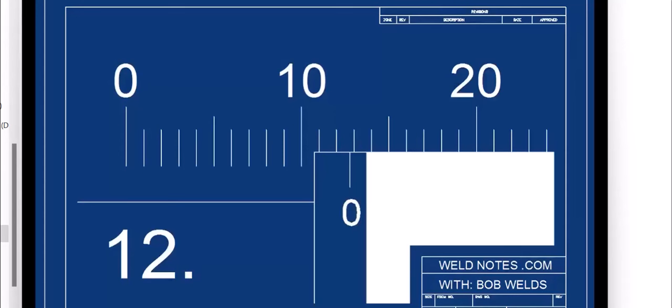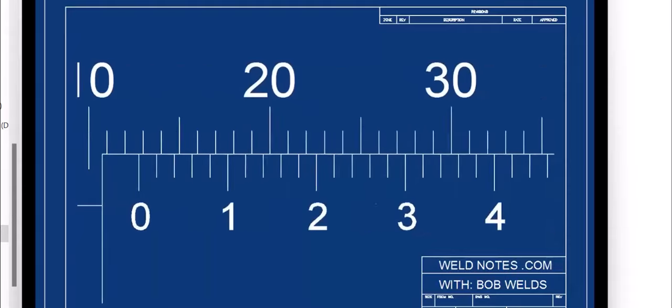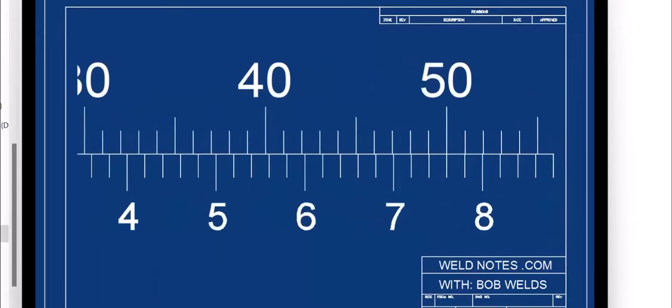But first, remember the trick? See how the reading is beyond halfway between the marks? That means we need to look on the high side of the vernier scale. I'll slide the view down there and let you look. Now here we go. Pause the video and look carefully. The mark that lines up best is here. Now, what number is that? This is the 0.7 mark. So 0.72, 4, 6. The answer is 12.76.